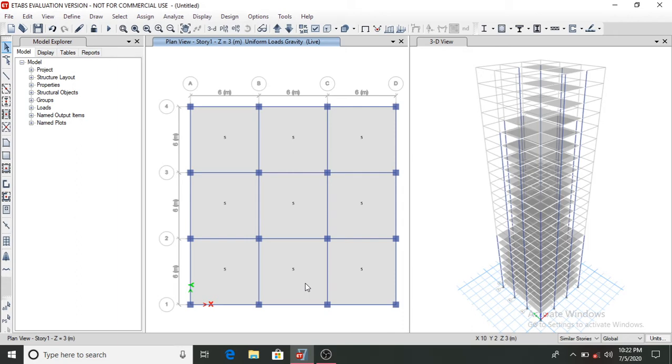We are going to use auto draw cladding option in this design. So we need to assign a dead load of 0.2 kN per meter on the exterior beams of all the stories. This is the load coming from the claddings onto the beams. So we need to select all the exterior beams of all the stories. Though the load is same, that is 0.2 kN per meter for all the exterior beams, we can't use that all stories option here because the exterior beams are different for different sets of similar stories. So use the option similar stories itself.